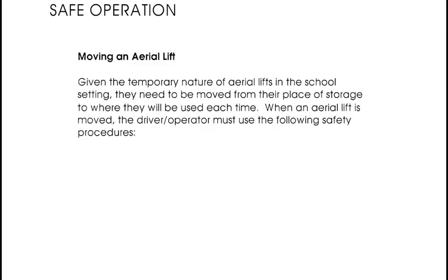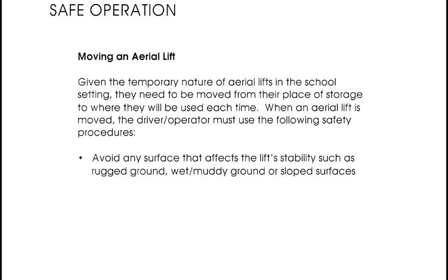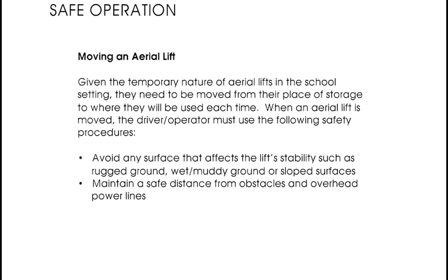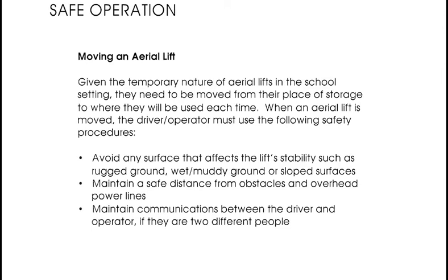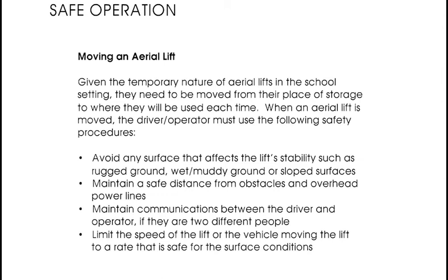Given the temporary nature of aerial lifts in the school setting, they need to be moved from their place of storage to where they will be used each time. When an aerial lift is moved, the driver or operator must use the following safety procedures. Avoid any surface that affects the lift's stability, such as rugged ground, wet or muddy ground, or sloped surfaces. Maintain a safe distance from obstacles and overhead power lines. Maintain communications between the driver and operator if they are two different people. Limit the speed of the lift or the vehicle moving the lift to a rate that is safe for the surface conditions.